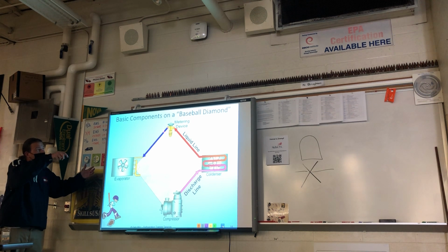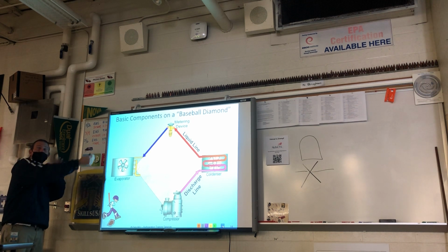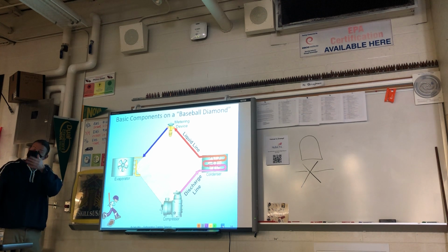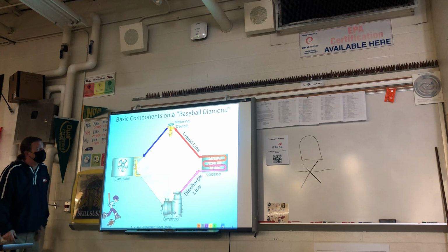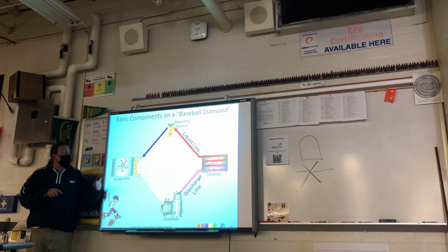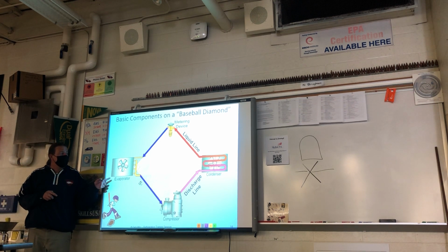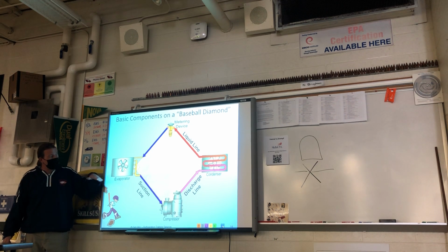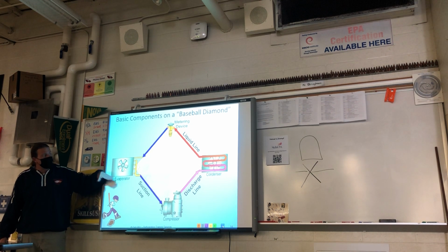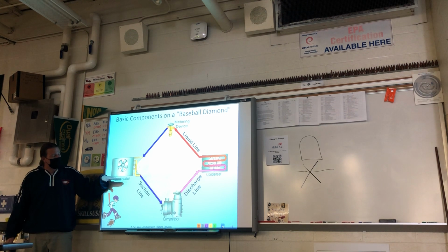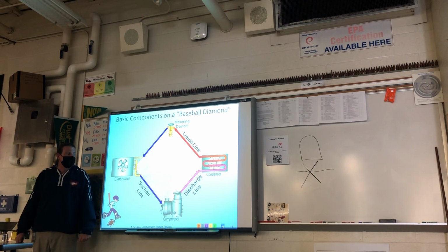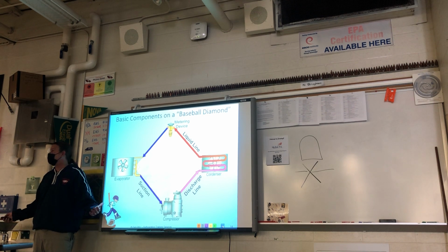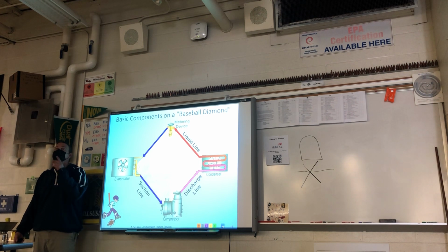Could be just a cap tube, and the length of the cap tube and the size of the hole in the cap tube is going to determine how many of those molecules go through from the high to the low side. And then after this evaporator absorbs all the heat that it needs to and boils off the gas, it should be nothing but superheated vapor. Boils off all the liquid to gas. It should be nothing but superheated vapor going back to the suction line, all to be redone at the compressor for compression to be kicked out of the discharge line.